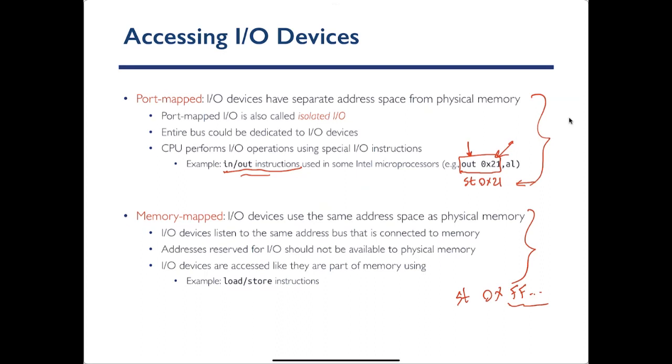Now, if the device wants to talk to memory, usually it happens through a DMA engine, right? So the device talks to the DMA, and then the DMA talks to memory, back and forth. We saw an example of this in, I think it was lecture 2, if I'm not mistaken, when we were talking about I/O communication.